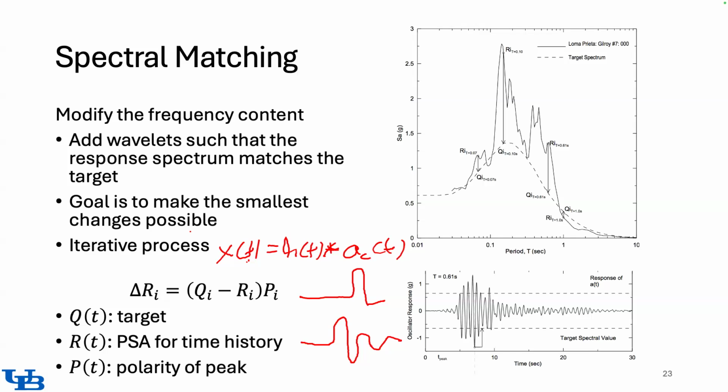You can use a wavelet that is the inverse of this, and then the correction that you're applying becomes the delta function. So if the correction that you're applying to the time history is something that looks like this, and then suddenly stops, and then you convolve it with this one, the different peaks will constructively interfere so that you are left with a correction that is closer to a delta function.